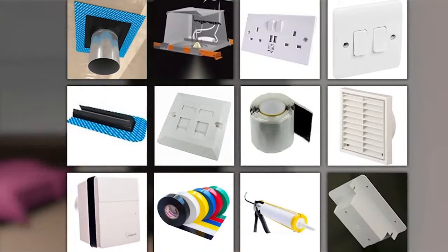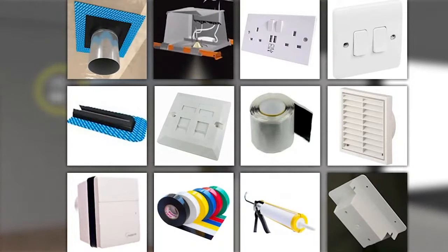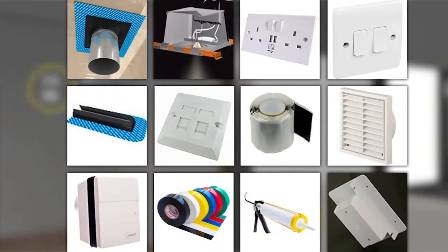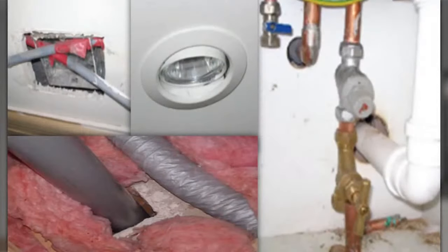contractors. For example, in Scandinavian countries, where low air leakage rates have long been standard practice, every plumber and electrician will be used to working carefully around air barriers. However, in the UK it's not uncommon for holes to be cut and drilled and work undertaken with no thought given to any knock-on effect on air movement.